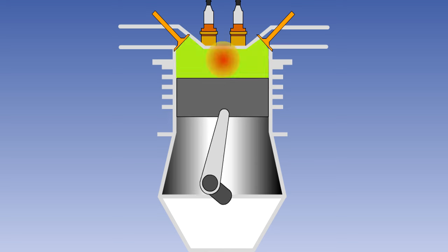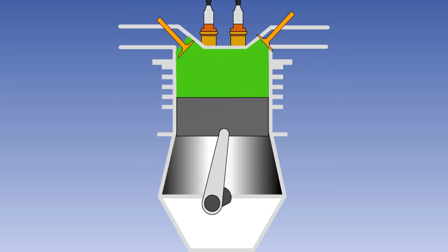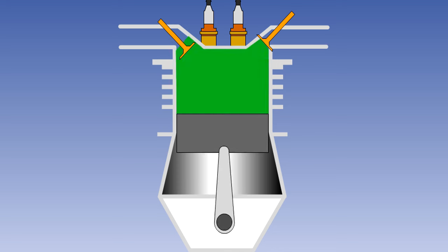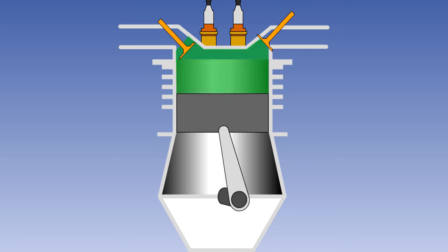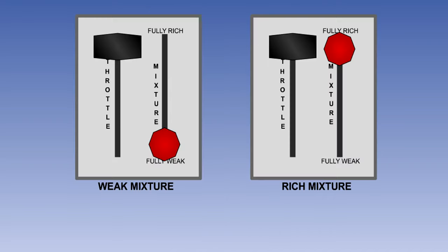Aviation gasoline is graded by octane rating. The octane rating of a fuel is a measure of the fuel's resistance to detonation when subjected to high temperature and pressure. A fuel's octane rating is checked in a test engine with the fuel-air mixture weak and with it rich. This gives the fuel 2 octane ratings. The weak figure is used in the fuel's name. So for instance, Avgas 100 is a 100 octane fuel when the mixture is weak, but a 130 octane when the mixture is rich.